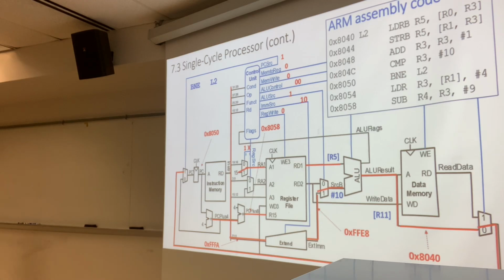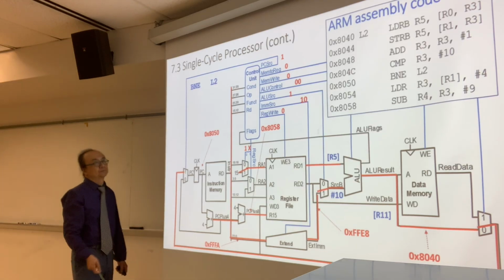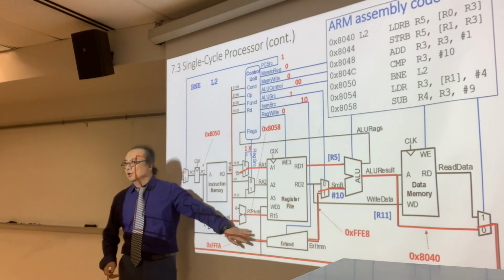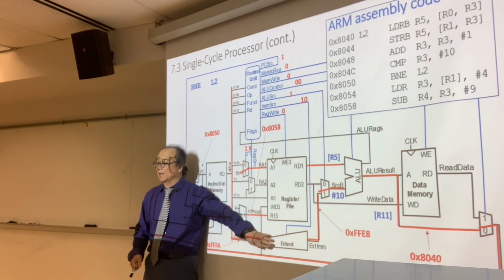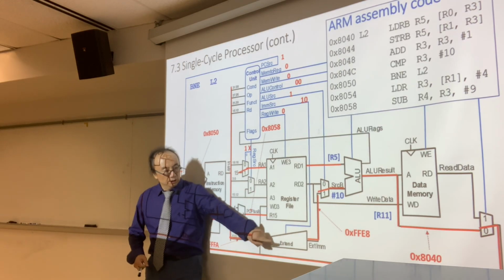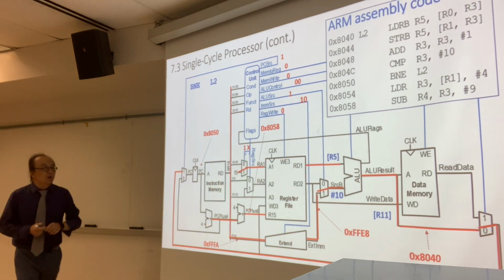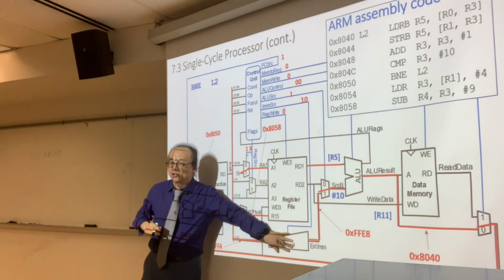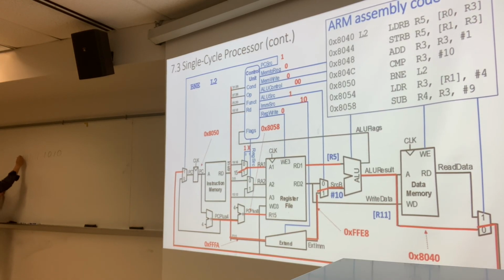And if you are using this example, these values again, from here to here. Shift left by 2. When we have a branch, in the data processing instructions and memory instructions, it's all zero extended, and there's no shifting mechanism in here. That is controlled by this blue line, right? It's 1, 0. But in the branch, if we have FA, and when we went through this extend unit, it is sign extended. You're going to make it 32-bit. Then we can just add the total number of ones and fill up the front part.